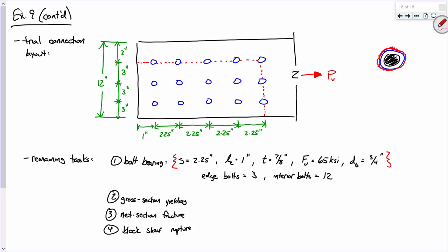All right, and the last one, which is not a limit state, but we also need to check this. Of course, we can't check slenderness for this problem because we don't know how long the member is. This member could be 5 feet long or it could be 50 feet long. But let's also go back to some mechanics of deformable bodies. You don't have r, right? You don't have the radius of gyration.